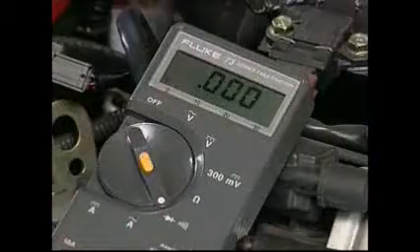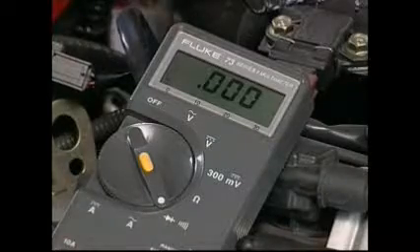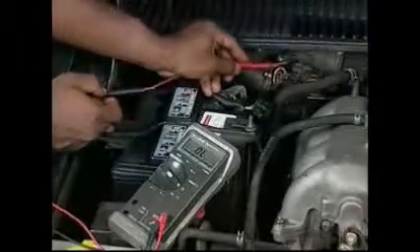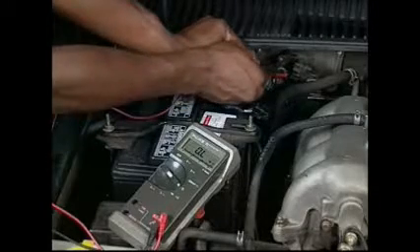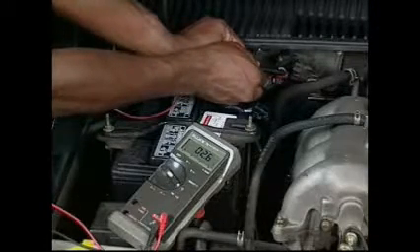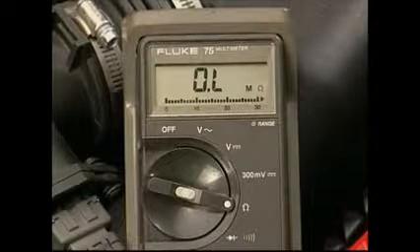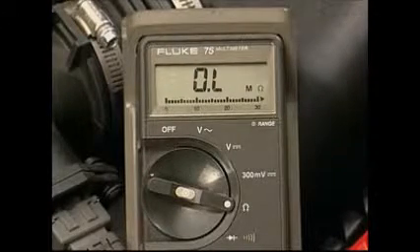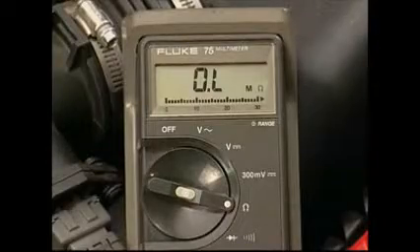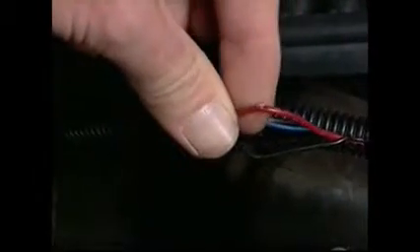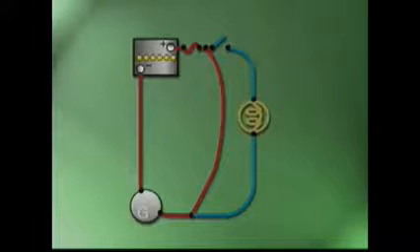A reading of 0 ohms for a segment that is a single wire indicates continuity. If the segment includes a load or other resistance, the meter will show the resistance for the entire segment of the circuit being tested. If the reading on the meter is OL, that means that the resistance in the circuit is over the limit of the meter. In a continuity test, that means that there is an open in the circuit of infinite resistance that current cannot flow across. Similarly, shorts to ground, where a portion of the circuit is bypassing the load, can be detected with a continuity test.